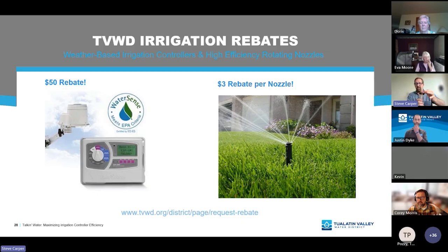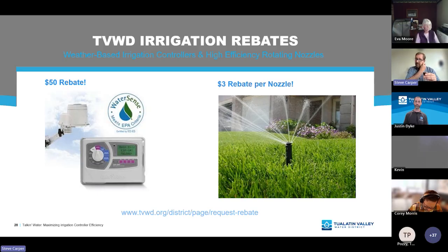If it's really overgrown, and again, debris is probably getting down onto that nozzle and the stem as it operates, that may be more the issue, as opposed to it being too high. You want to just evaluate that. But if the sprinkler head is down and nice and level with the soil, it's probably good. Then you just want to test it. Operate the zone and see, does the stem come up and activate when it's on, and then retract fully when the zone turns off? Then you're probably good to go from there.